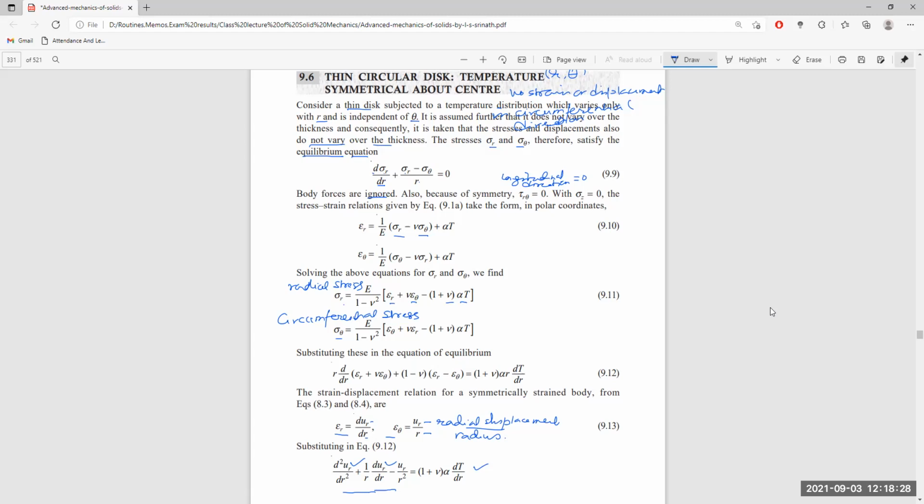As we know, the stress in r direction and theta direction is possible, as well as displacement in r direction, that is u_r, by keeping the displacement in x, y and z direction equal to 0, and both sigma x and ux are equal to 0 itself. But body force here, like gravitation and the surface tension, etc., is ignored, and thus it also becomes axisymmetric itself.